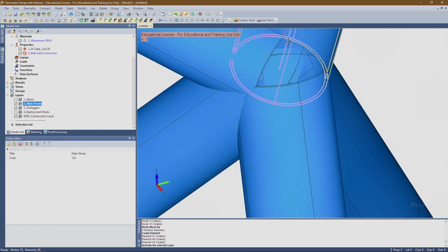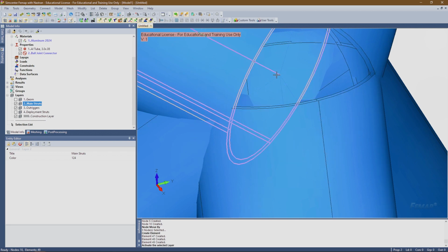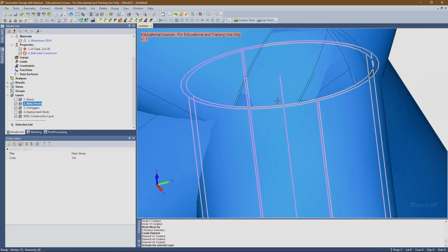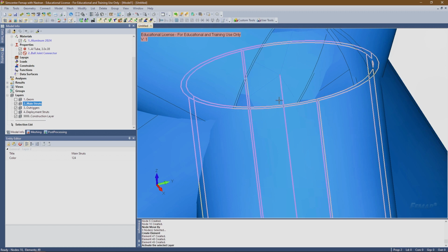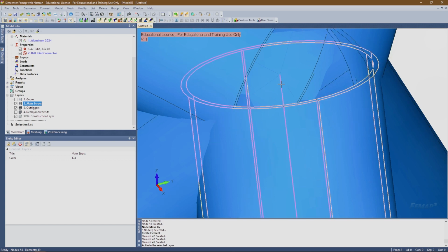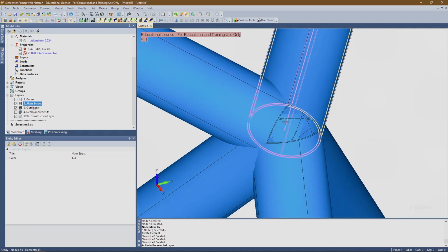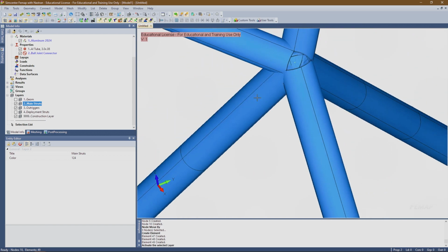So essentially we want to create a spring, but we don't want our spring to have 0 length, because then NASTRAN is going to get extremely confused because it doesn't know what directions the spring has, because generally direction 1 is along the length of the spring, and so is direction 4, and then directions 2 and 3 are based on the vector direction of the spring. So if you make a spring that has 0 length and just connects these 2 points, then it's not going to know what any direction is.